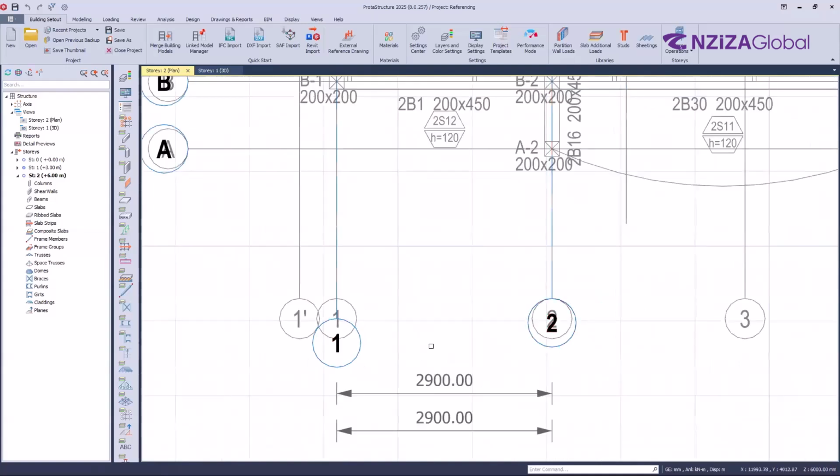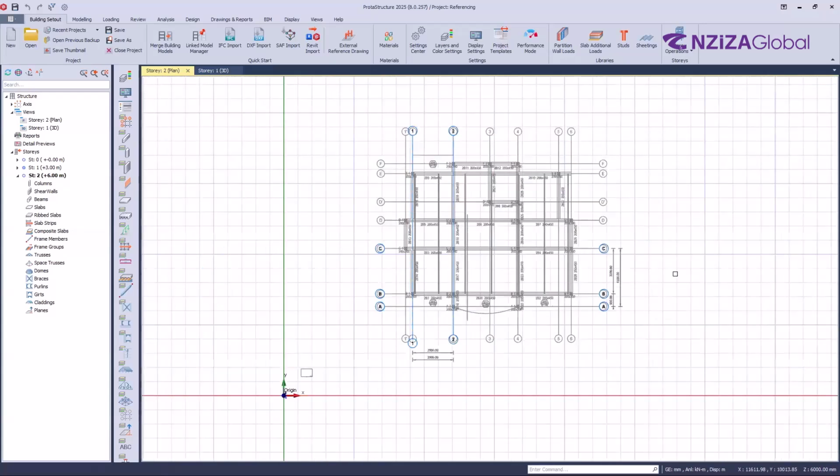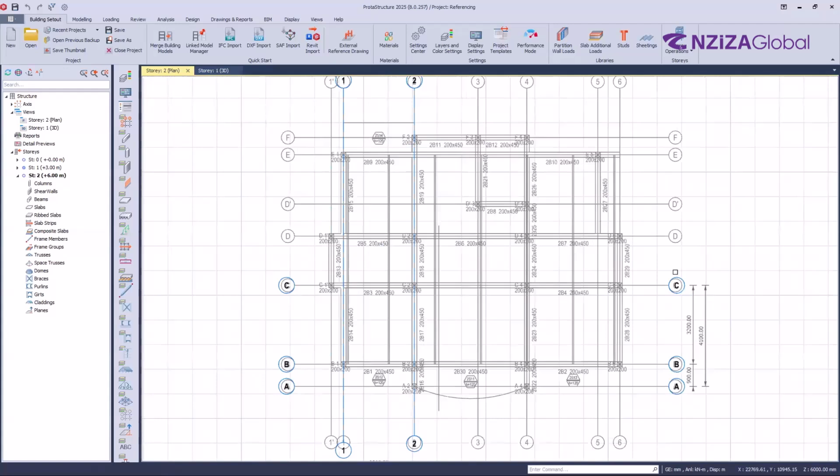Okay. So now I'm sure that the drawing on story 1 is aligned with the drawing on story 2. Then if I had to model columns, then I can continue modeling columns, beams, whatever. Good. So that's how you can